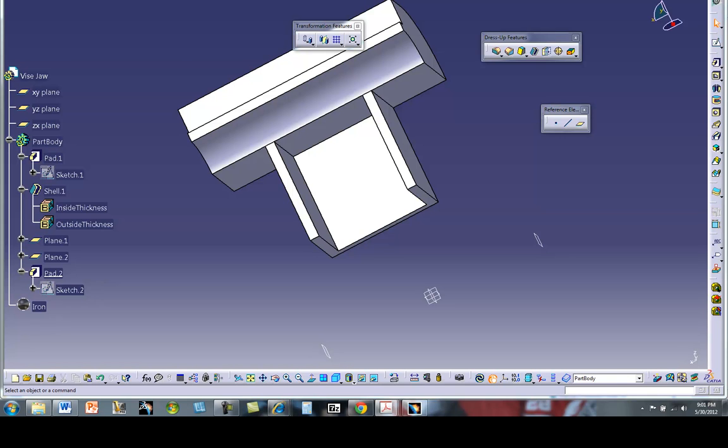Now what we're going to do is actually cut out parts of this object to end up with what looks to be as in figure 4.96. I'm going to do it different than what is done in the book. And I'm referring to this horizontal plane as my sketch plane. And I'm looking at figure 4.95, but I've learned some things since I've actually done this assignment. And so I'm going to show you a different way to do it that uses a lot of project 3D commands.